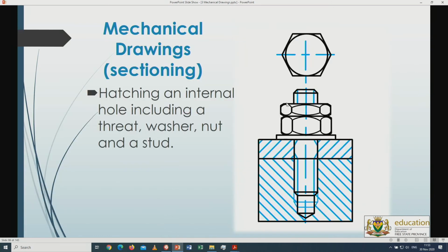Now this is the purpose of the lock nut. The purpose of the lock nut is basically to add some tightness towards this part over here, so it doesn't rattle and become loose in the process. So it's tightened up one against each other, and to make it stronger. So of course we don't need to waste money on thick nuts that we're going to use over here. We're going to make it smaller, so therefore we're going to save some money by adding a smaller one.